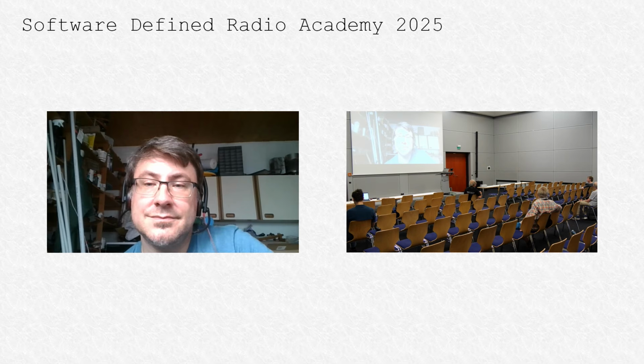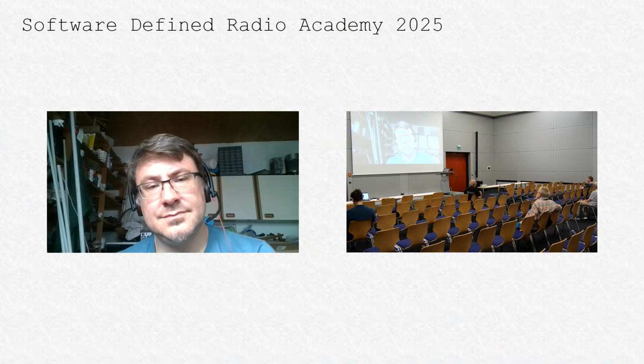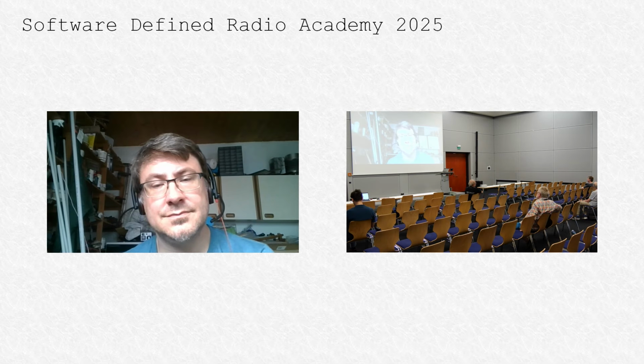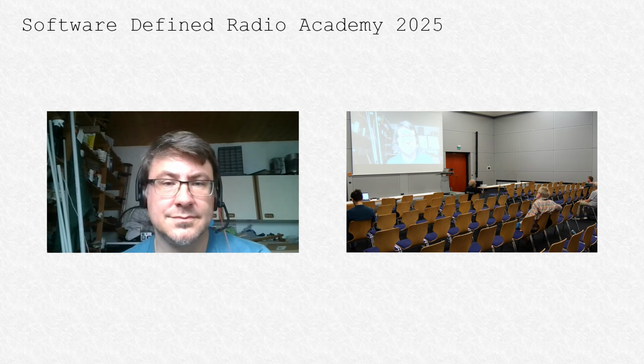You've actually used a Foursquare here. And if I understand correctly, amateurs use Foursquare because basically you're getting a lot of gain for the number of elements. But if I remember back to university, it's a very long time ago, in sonar and radar systems they use planar arrays. Have you looked into that, if that might be better for direction finding?